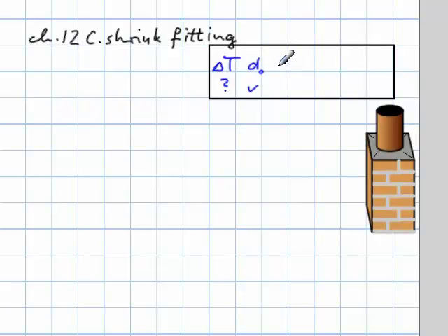What is given is the change in the diameter, delta D. What else is given is the material, the steel here, and now we have to look at an equation, and that's the equation on thermal linear expansion, which is delta L equals alpha times L naught times delta T. And of course, our delta L and the L naught here, the length, are the diameters and the change in diameter that we have here.